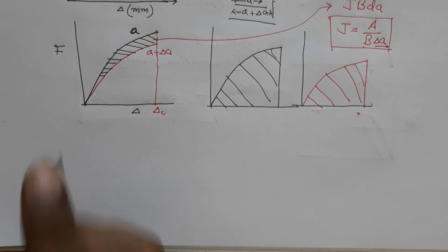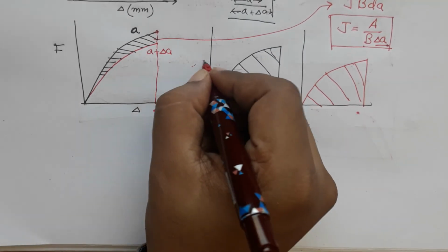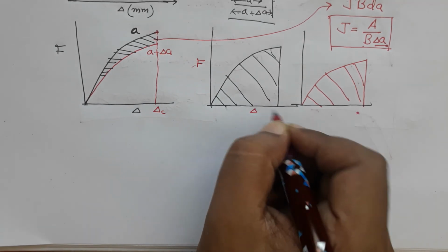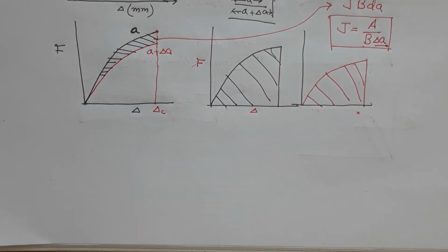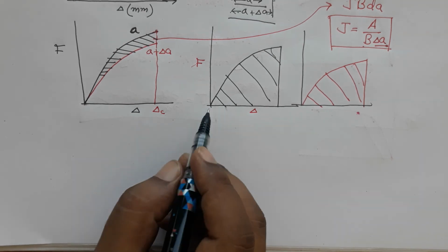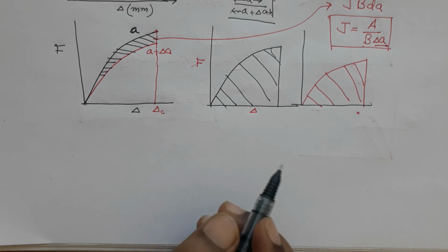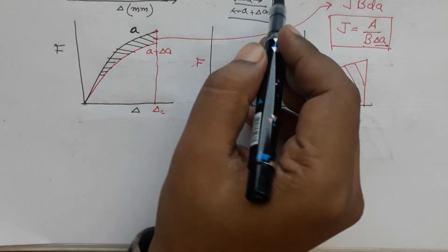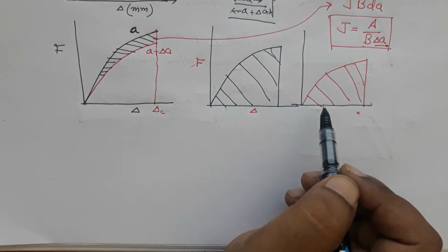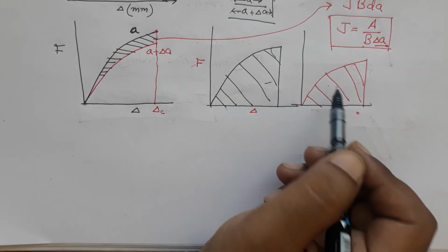As we do the experiment, consider this one, because we are still dealing with a single crack length specimen and we do not want the crack to grow, because if it grows then the J integral is not valid. We want to know how the J value changes at different crack lengths. Okay. So, what we will do is we will do the testing at different crack lengths.